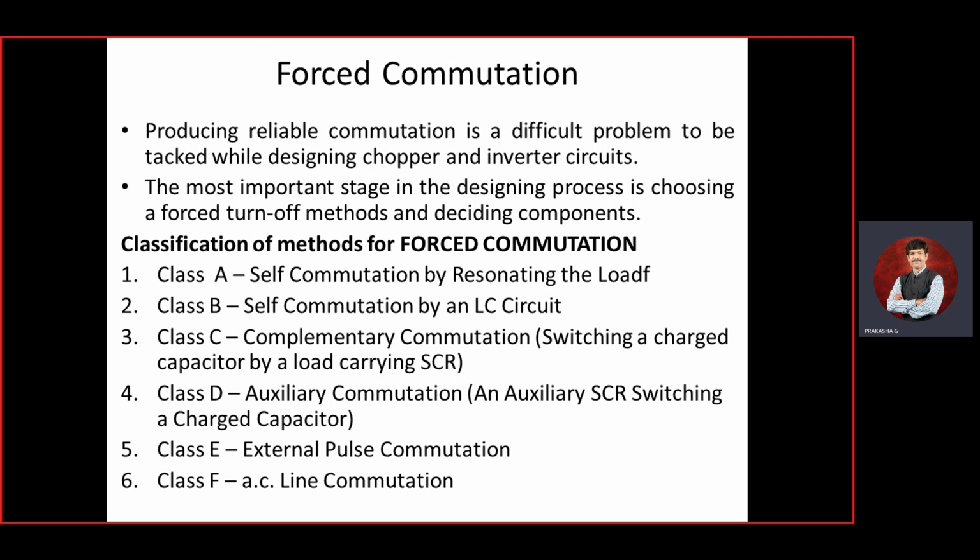But the other things: self-commutation by resonating load, self-commutation by LC circuit, complementary commutation by a load-carrying SCR and capacitor, class D commutation with an auxiliary SCR switching a charged capacitance. These things are self-learning. They are not in the syllabus. But what you can do is design those circuits.